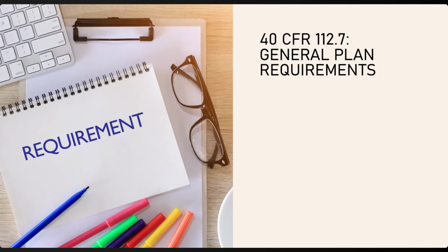An SPCC plan must be prepared in accordance with good engineering practices. The plan must also have the full approval of management at a level of authority to commit the necessary resources to fully implement the plan. 40 CFR Part 112.7 includes the general plan requirements that apply to nearly all SPCC plans.